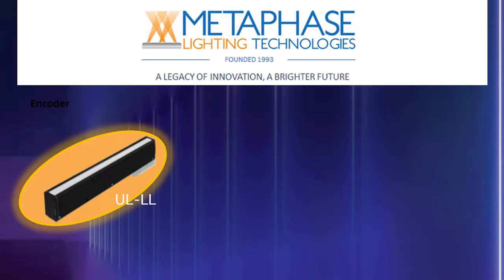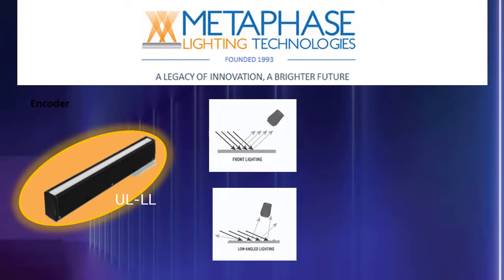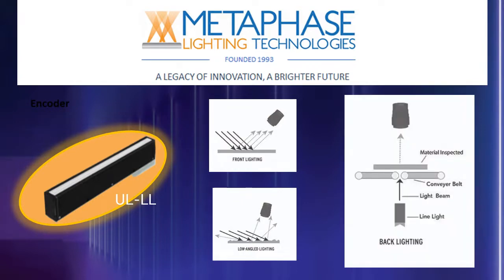The Metaphase UL-LL delivers a narrow, structured beam. Its high intensity and concentrated light make it ideal for the narrow field of view of a Linescan camera. Its high intensity and uniformity allow it to be used as a front light to inspect for material defects, angled to obtain an off-axis effect to highlight surface defects, or it may be placed beneath the object for a backlight effect to inspect for holes, voids, or contaminants.